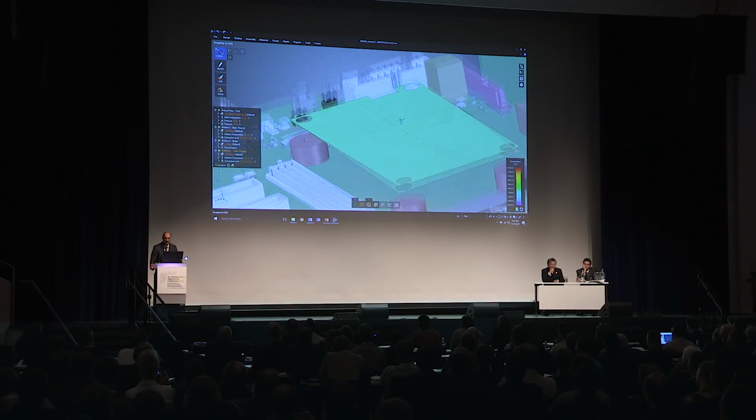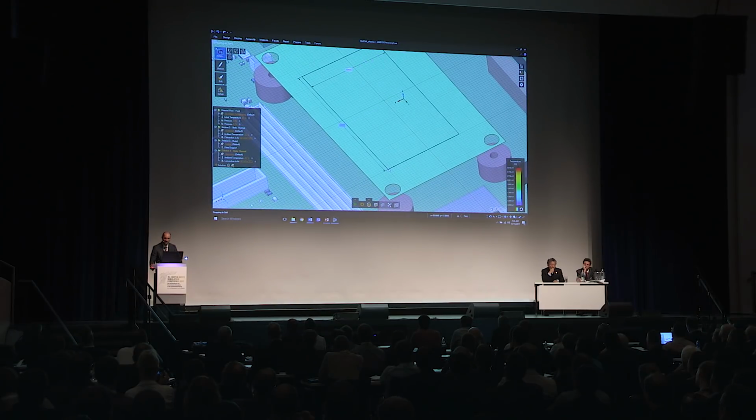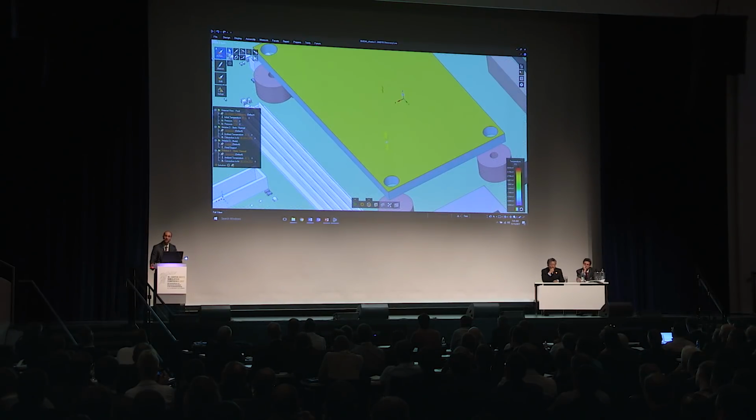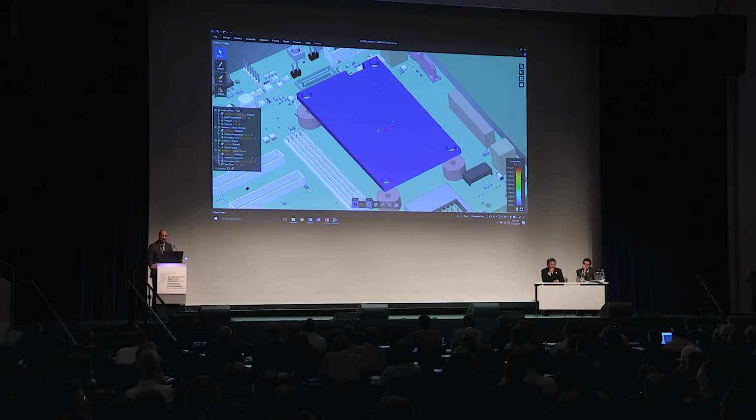Next, we will go ahead and model a contact region, right? Which part is going to be touching that chip, the part that's going to be hot. Then I'll pick this face, and we'll assign one and only one boundary condition. So let's say we apply the amount of heat in watts that's being generated by that GPU. They do get hot, by the way.